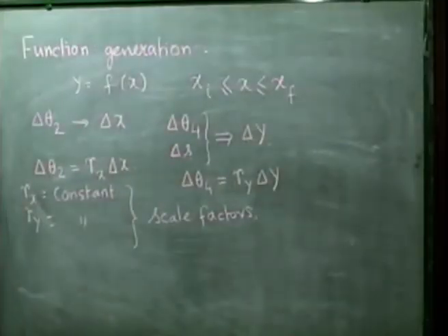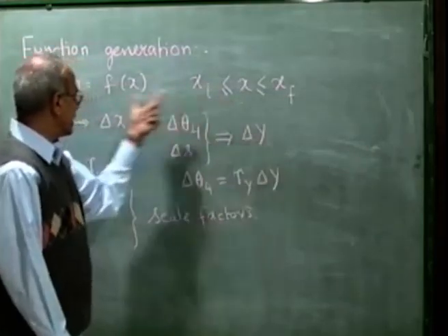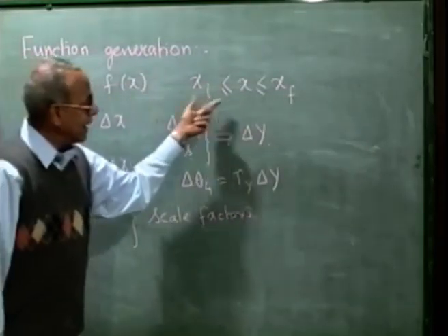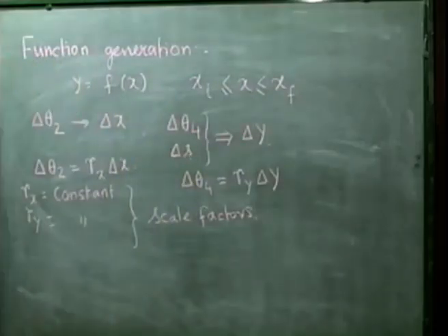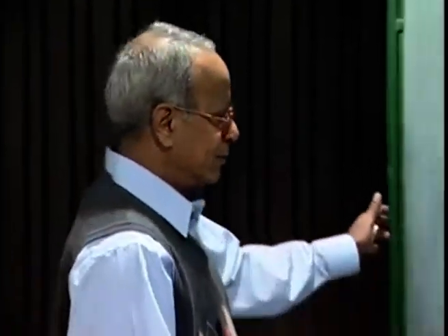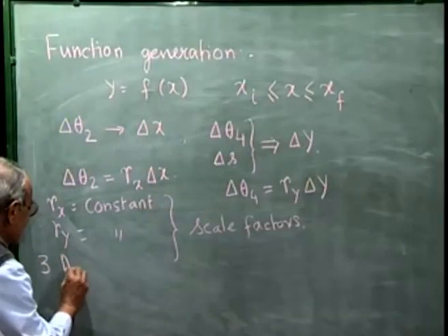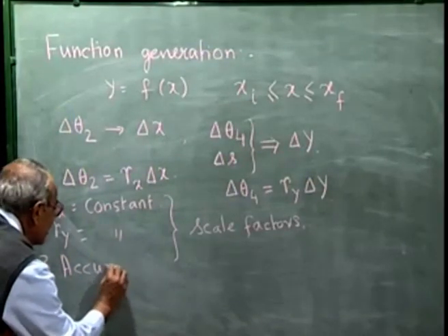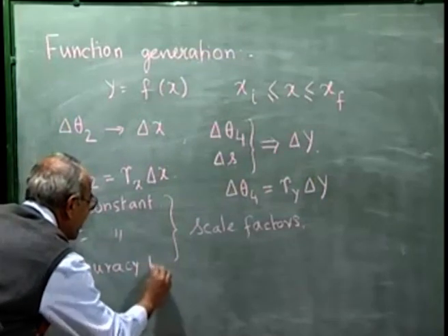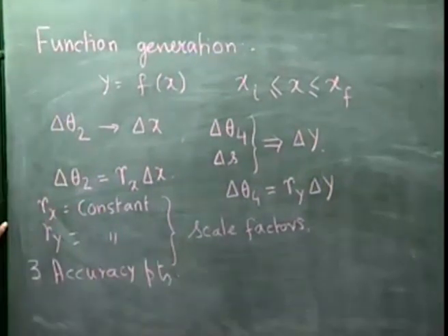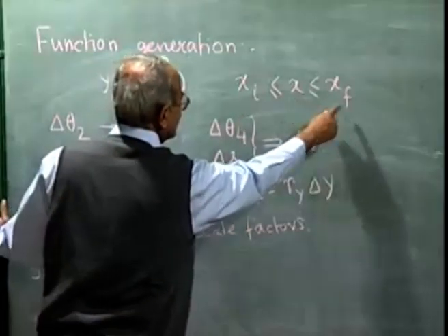In this precision point approach, which we are discussing in this entire course, what we mean is that I cannot generate this function in the entire range. So, we take some accuracy points, and as the first choice I said we should take the Chebyshev's accuracy points, where suppose for 3 accuracy points I should take x1, x2, x3 in this range.